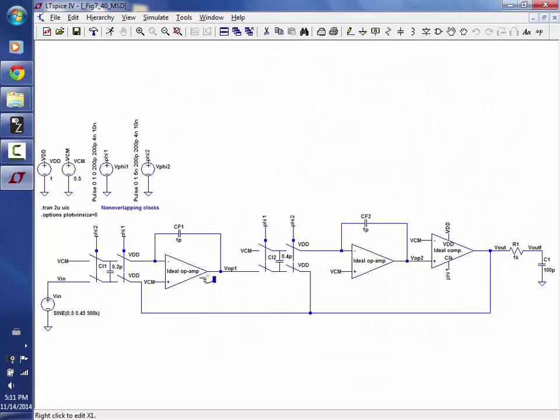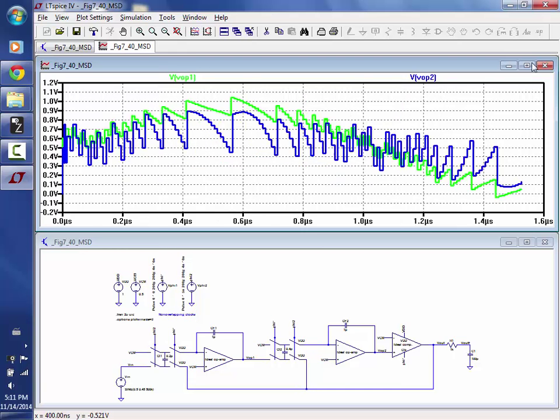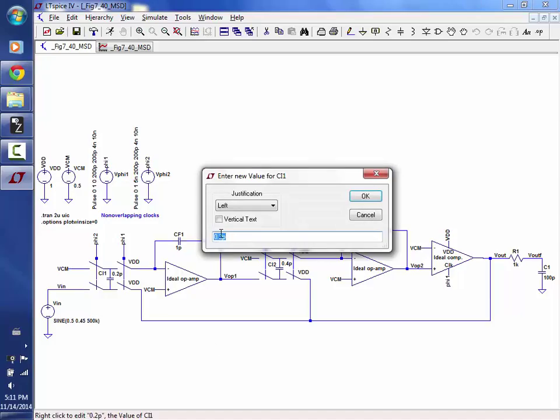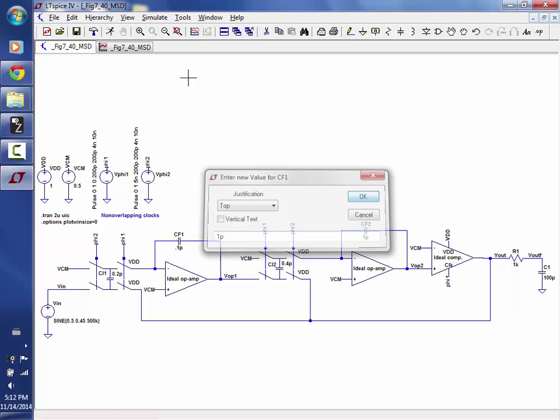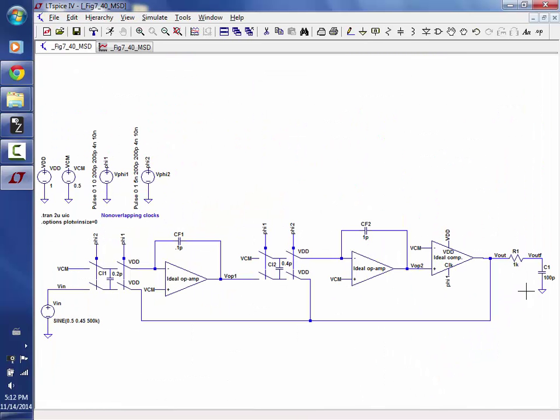If you look at this topology, it says G1 is 0.2, G2 is 0.4, G3 is 3. I run the simulation, I look at the outputs of the integrators, they look good. But you ask, well, I'm above the supply range here, and why don't I just increase these gains? No, what am I saying? I want to reduce these. Why don't I just put this at like 0.1, etc., and rerun so I get a smaller output signal, and then of course my output here goes lower.